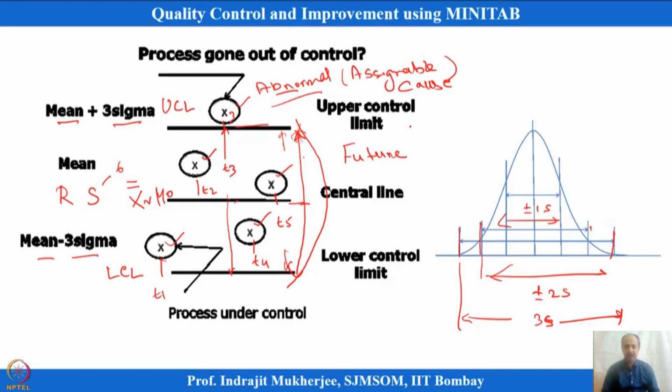Okay. So, it is difficult to identify assignable cause, but if we can stop the process at a given time point whenever there is an assignable cause, brainstorm, and have quality circles to identify and take corrective action immediately. These are small initiatives known as quality circles, where people associate together and try to solve small problems like that. That can take place immediately, and we can take some corrective action on this assignable cause, so that it does not recur.